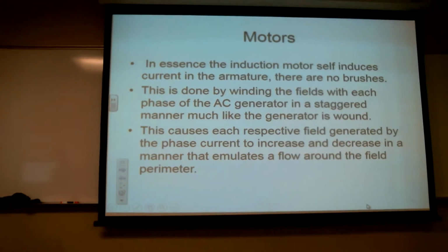Now instead, if I took all those iron bars out and just put a big magnet inside there, and then spun my magnet outside, the inner magnet would stay locked with the outer magnet, south to north, north to south. In other words, they'd stay in synchronous.